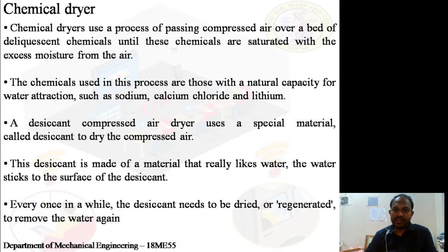These work on a different principle. Basically, desiccant air dryers absorb moisture from the air stream onto a desiccant material in a reversible process. They produce low dew points, so they are a good choice for sub-freezing conditions or when processes require extremely dry air. Even in this, we get two types: one is heatless and the other is heated desiccant dryers.